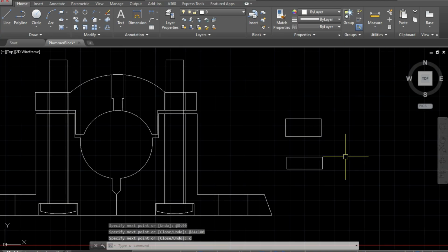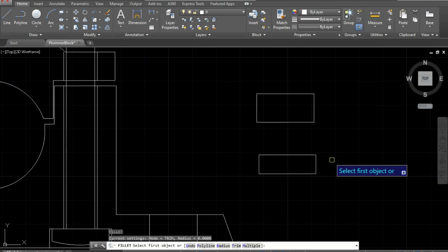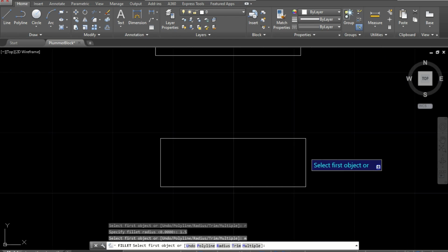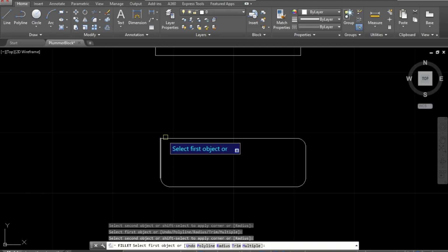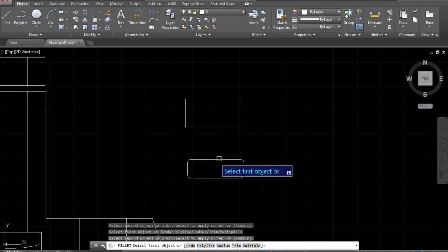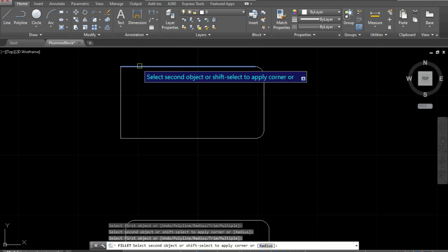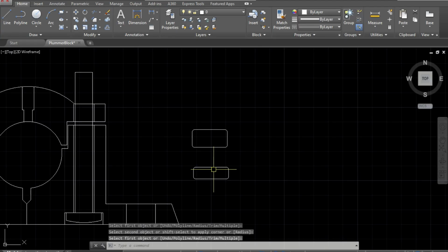These are the two bolts. Let us give some fillets. Give a radius of minimum 1.5 mm. Let's take multiple so that we can give it in 8 places. This will give a shape of a heart. Enter it. Let's restrict with these features.